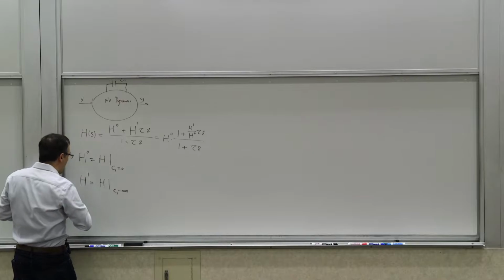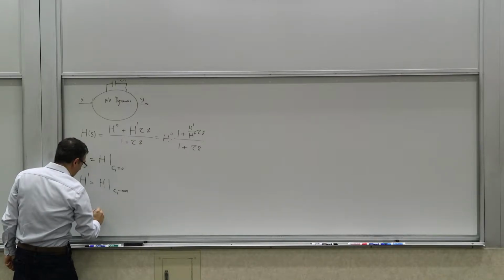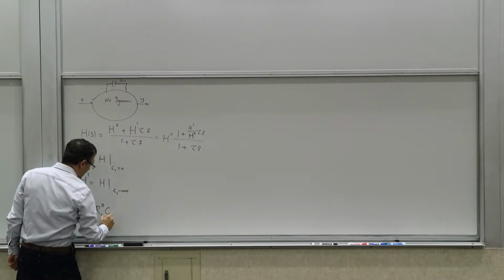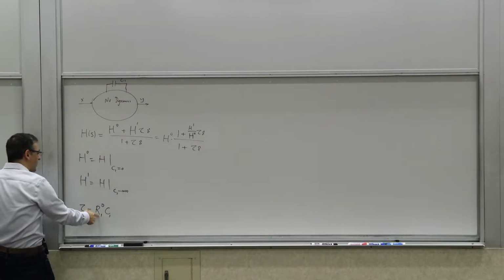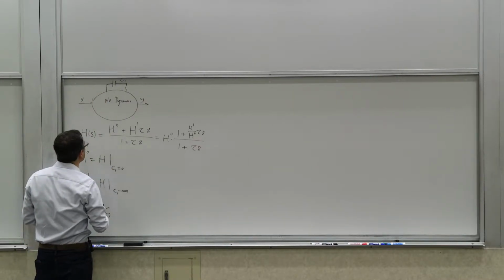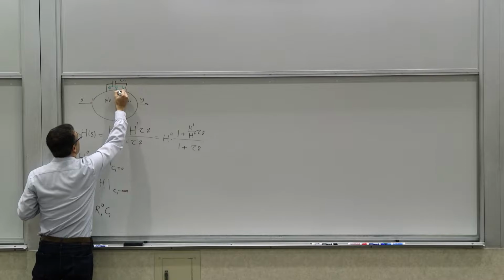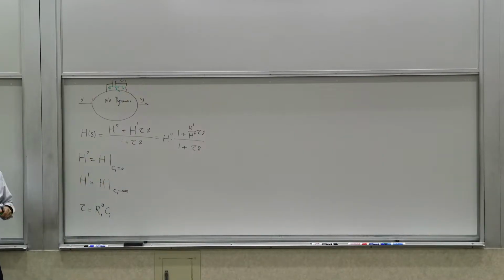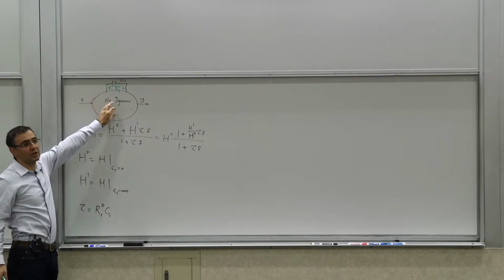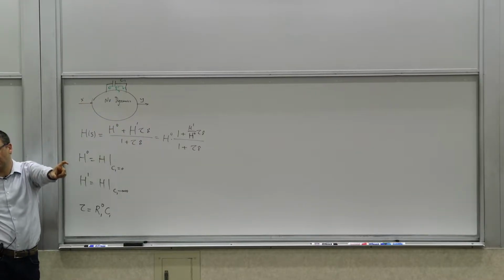Now, tau is the time constant associated with the circuit, which would be determined by the capacitor in this case, or what we call R10, because the capacitor is index C1. And what is this R10? It is the resistance seen looking into those ports where the capacitor is connected, with all the independent sources, including the input, being 0 valued, being nulled. Meaning that if you have a voltage source here, you short it. If you have an independent current source somewhere inside, you open it, and see what's the resistance you see across.